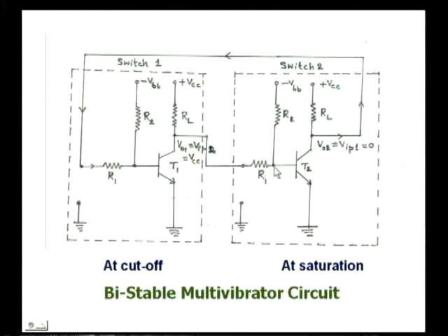Hence the voltage applied to the base emitter junction will be positive, and it is sufficient to drive the transistor into on state. And for an on transistor, the output VO2, which is input to the first stage Vinput1, is equal to 0. So this 0 volts is available at this point with no input signal. Here the potential divider R1 R2 in conjunction with minus VBB can provide a negative voltage at the base of T1, and hence the base emitter junction will be reverse biased.